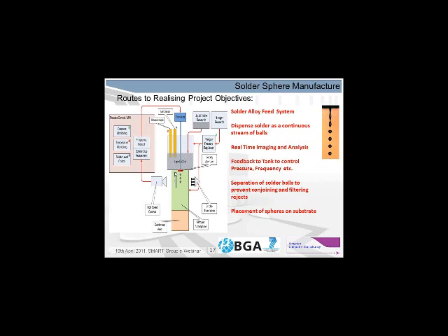After ejection, you can see here an electric plate. The solder balls will have a charge imparted to them to prevent conjoining, and by placing a charge and deflecting the solder balls depending on their size, we are aiming at being able to perform an initial filtering after making sure the balls are separated.